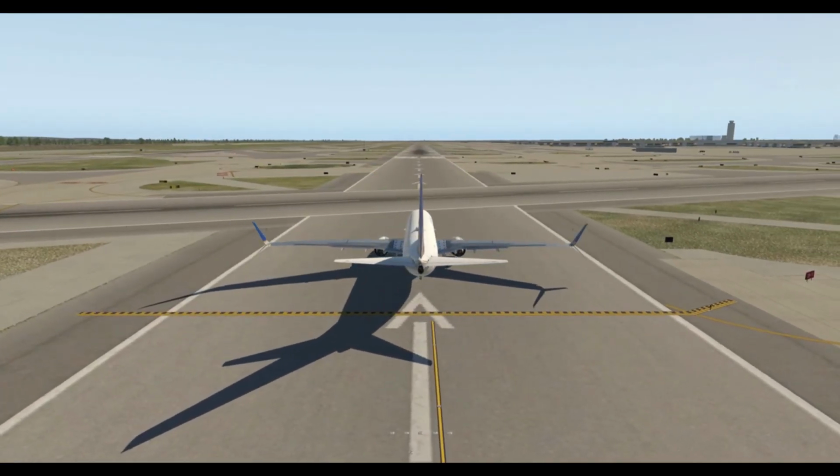So let's get started. Everyone should have a flight plan they can review. The aircraft is positioned for takeoff on runway 22 right in Newark. Our departure is over Colts Neck and White intersection. Cruising altitude is flight level 340. Landing fuel is approximately 6,500 pounds. That's about an hour and a half, and our alternate is Aguadilla, which is 10 minutes from San Juan.